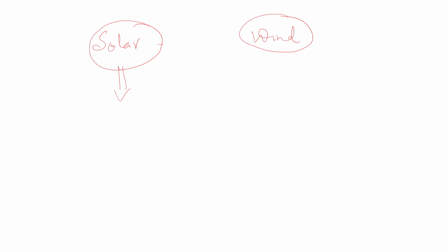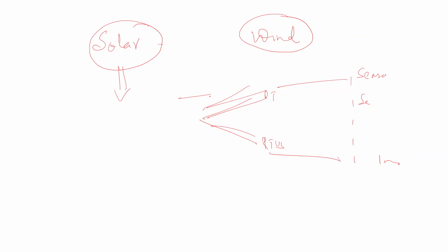What it does here, it actually monitors and controls the distribution substation. Okay, and how does SCADA collect the data? There are three components of that. First is the master station, and there is the RTU, remote terminal unit, because the sensors will be placed in the field. But those sensors are very far away from the master station. There will be thousands of these sensors. All these sensors, through RTUs, send the data every hour, or every 5 minutes, or whatever time they have set, to the master station.